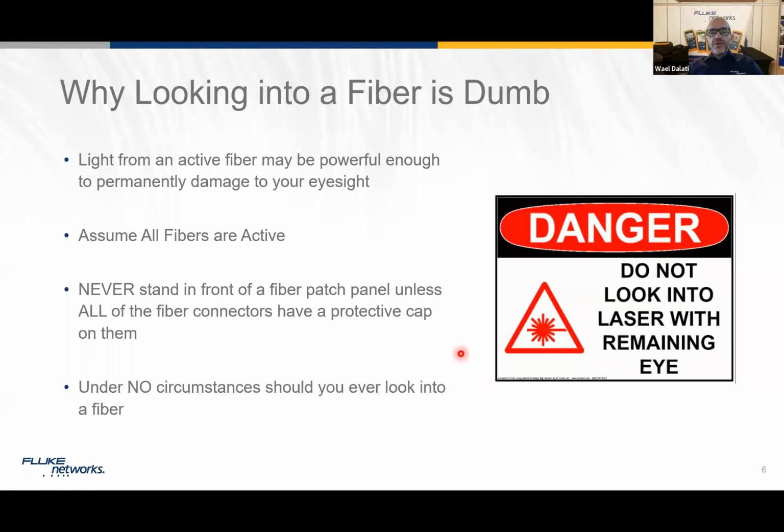So as a consideration, they consider always that the fiber is live and act upon it. Don't look straight in the fiber, don't look into it, stay away from it. Don't approach a patch panel with open ports. Make sure that they are all covered with dust caps. And whenever you need to do any work on the fiber, just go and use an electronic inspector with a camera and a screen that you can see what's going on, rather than using the optical camera, which can increase the damage of your eyes.